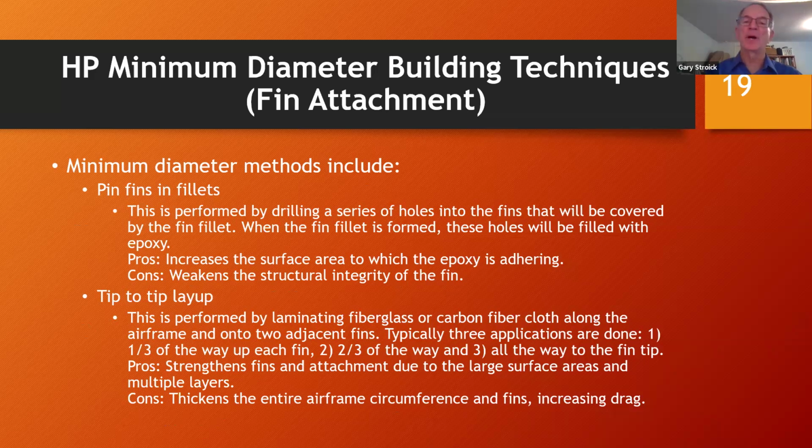And then when that epoxy dries, or cures, what you'll end up having is not only the fin fillet holding along the sides of the fin, and of course along the airframe, but also the epoxy going through, which will create more surface area for the epoxy to hold the fin in place. And the epoxy itself is holding the fin down and in place onto the airframe.